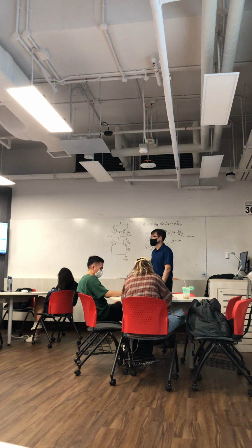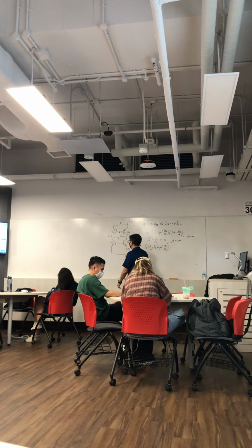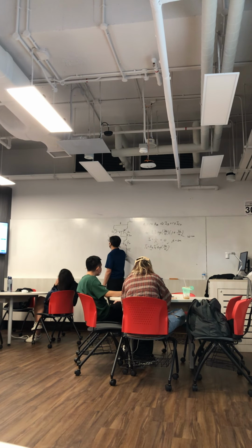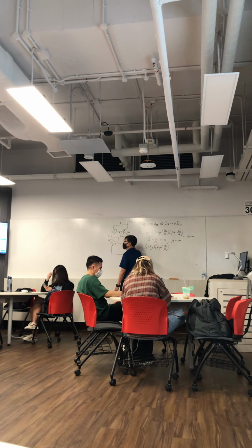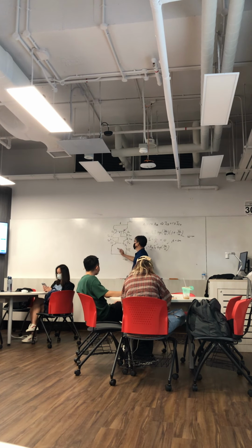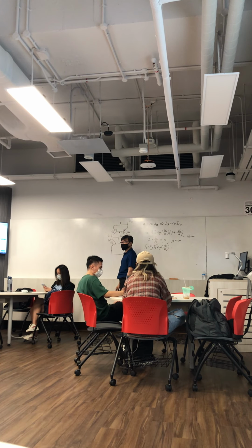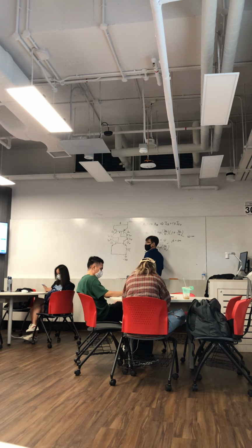Correct? Another thing I want to tell you is that this is IC, this is MPN, IC1, and this guy is IC2, right? Since there's no base current, aren't these two currents the same? So I must tell you that IC1 is equal to IC3, correct? The second thing is IC2 must be equal to IC4 as well, since there's no base current.